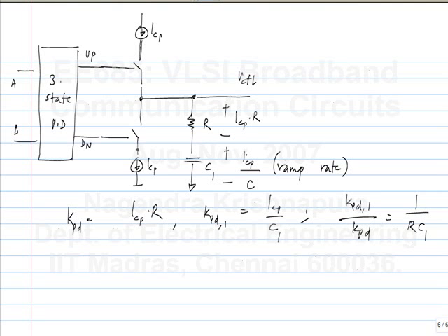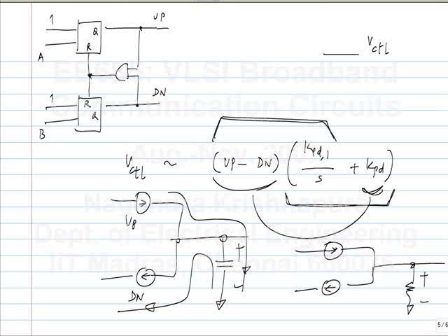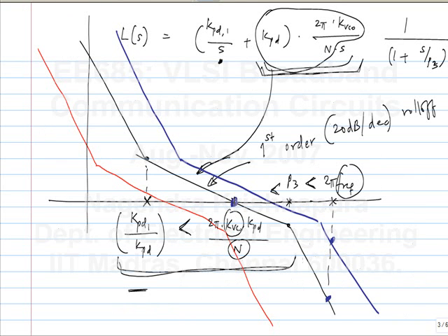Now this goes to the VCO. To change the free running frequency of the VCO, you need an average control voltage at the input of the VCO. After steady state is reached, the capacitor will have accumulated some charge, and that will provide the average input. If there are fluctuations, pulses of up or down, the voltage across this capacitor will be small. That is the meaning of having the 0 here. So 1 over RC1 is much smaller than 2 pi FRF. If you have fluctuations at FRF, effectively the voltage across the capacitor is much smaller than the voltage across the resistor.